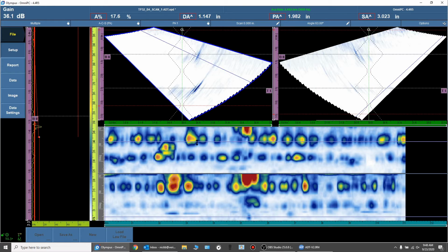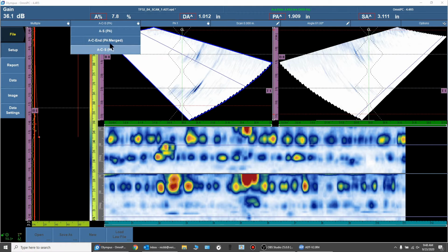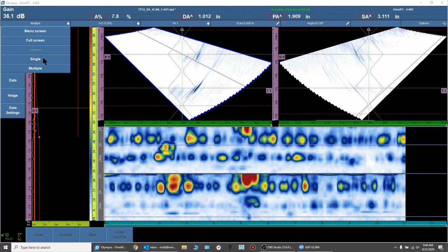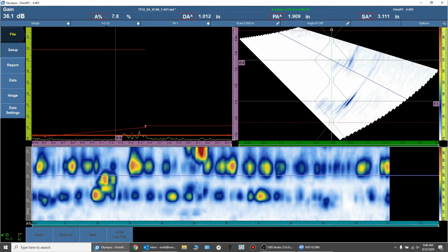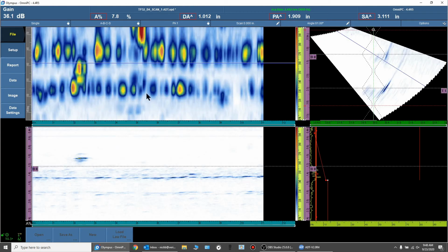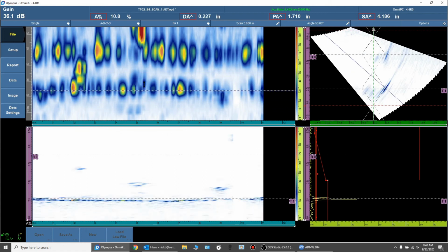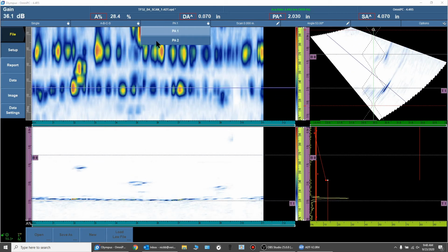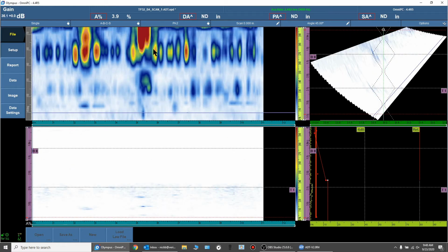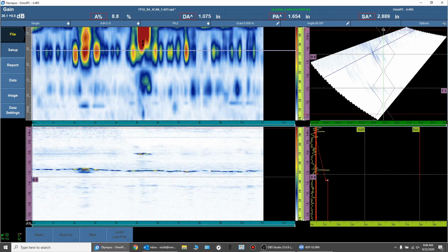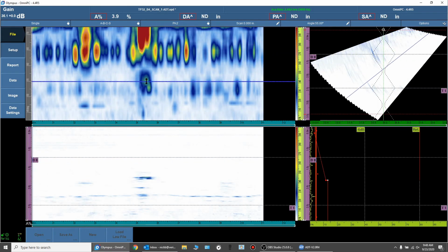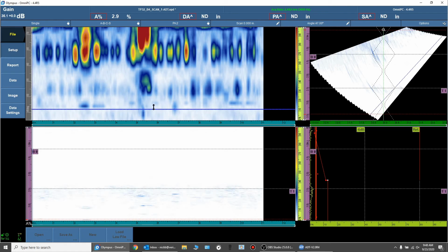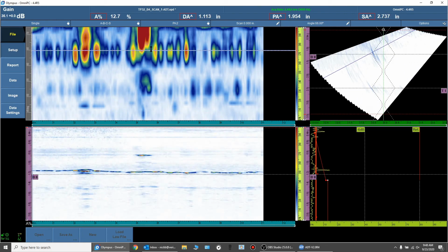So without ADT, you obviously have a blank indication table. You have to start finding the view you want to use, start manipulating these data cursors, and really just try to decide what's real, what's relevant, what's an indication. Once I find an indication, I might write down everything I see in group 1. I might do the same thing for group 2, have to go all the way through this, what's real and relevant, what's the same indication as the other group.